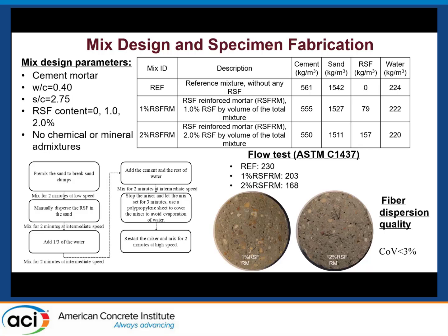And for the chloride, for the corrosion problem, yes, that might be a problem, but we haven't investigated it in this study. But I want to say that with the fiber reinforcement, our cracking width will be very small. So we will decrease the chloride permeability, which as a result can improve the corrosion resistance of these specimens. But I think maybe in the future we will evaluate the corrosion problem of the steel fiber reinforced cement mortar. Thank you very much.